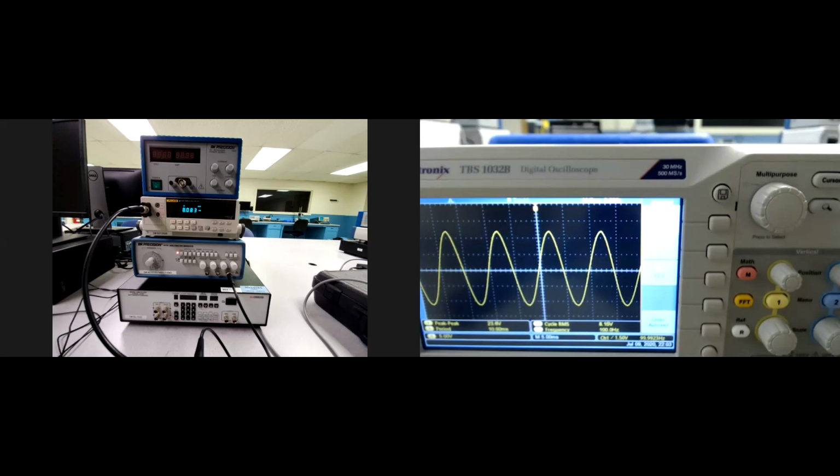And what we just did, that was step 4 of the procedure. Okay, so I'm gonna read it out loud. Observe the signal with the digital multimeter and oscilloscope. Record voltage peak, voltage peak to peak, voltage RMS, and the period of the signal. You can tell that the multimeter doesn't have a screen, okay? But for the final report, you will have to convert the voltage RMS from the multimeter into voltage peak and voltage peak to peak, because you want to compare the values obtained from the multimeter to the values obtained from the oscilloscope.